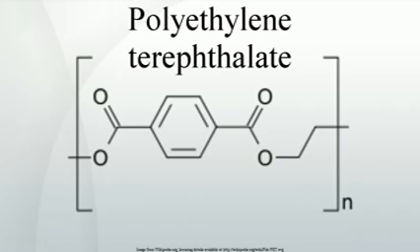PET consists of polymerized units of the monomer ethylene terephthalate, a colorless, semi-crystalline resin. Based on how it is processed, PET can be semi-rigid to rigid, and it is very lightweight. It makes a good gas and fair moisture barrier, as well as a good barrier to alcohol, requires additional barrier treatment, and solvents. It is strong and impact resistant. PET becomes white when exposed to chloroform and also certain other chemicals such as toluene.